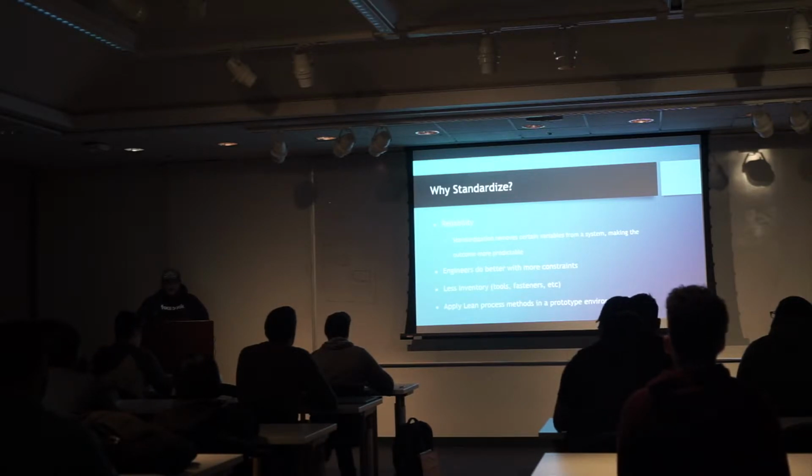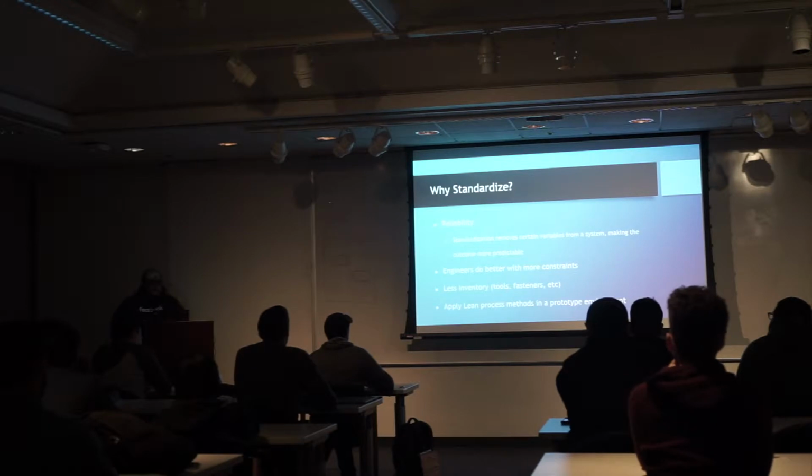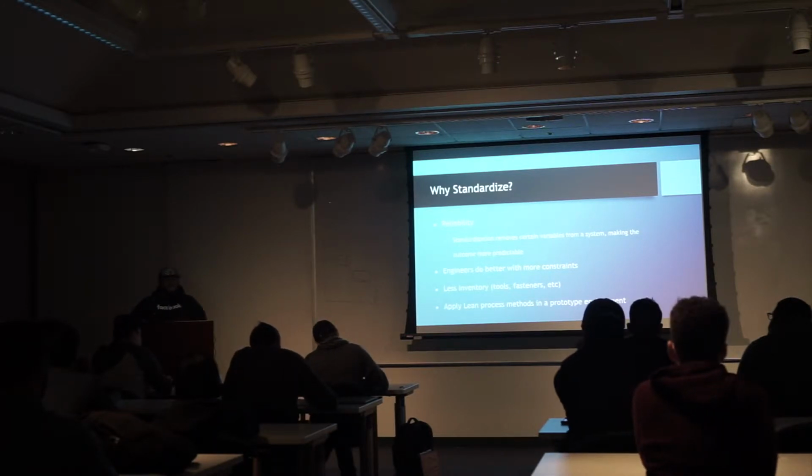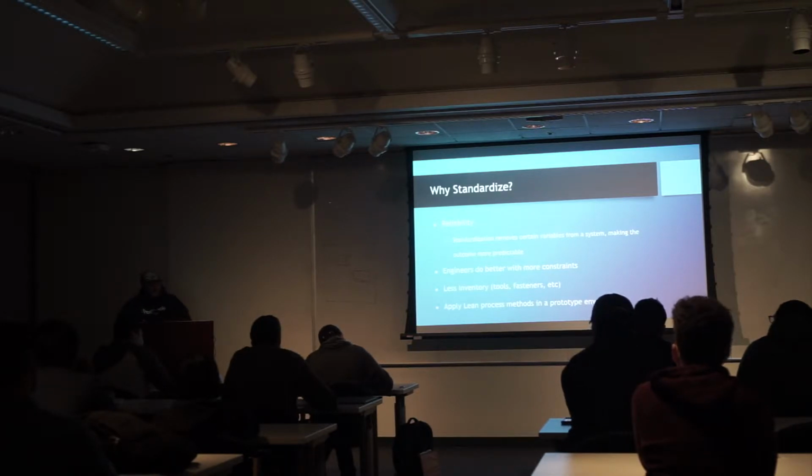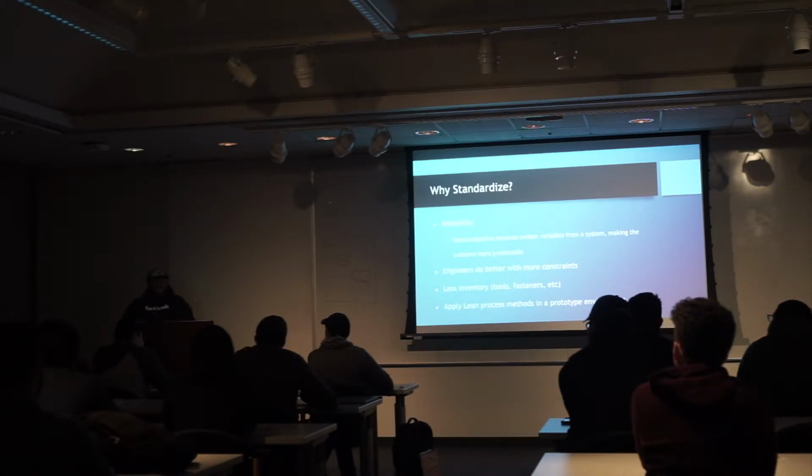So, why standardize? Reliability is a big one, especially in processes. Standardization removes variables from the system. For instance, at work, I do a lot of manufacturing on CNC mills. We have a process that is standardized to where I don't set up the machine, I don't build any tools, I don't find any work offsets. I just put material on a vise and press go on my program. It's so standardized and flushed out that we run unique parts that have never been proven overnight. So we press go and we go home.